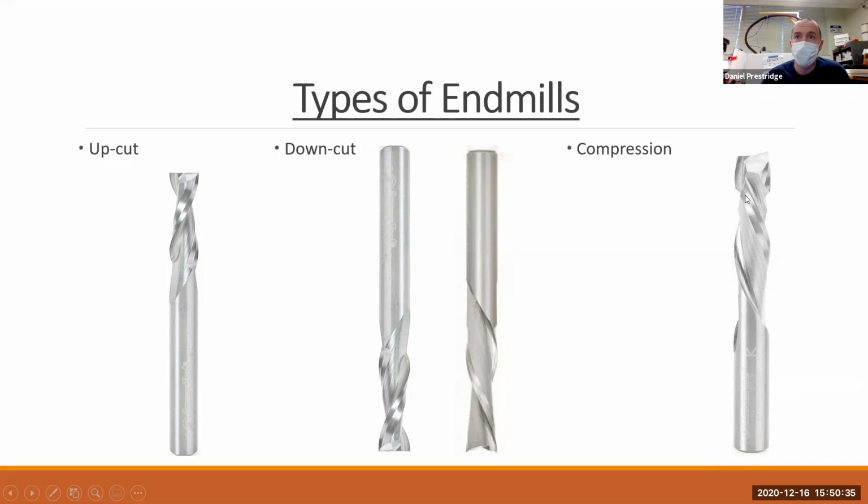That maintains the surface on the top of the workpiece because you plunge down enough that it's pushing down into it, but the upcut pulls up. So if you go all the way through the material and the bottom of the end mill is sitting at the bottom of your workpiece, then it doesn't push down through the bottom and create the same issue you would have if you were pulling up from the top. It's actually a pretty interesting end mill, but we really can't use it that much. It's more for wood and things that don't act like metals and plastics, where they get melty, stuck in the flute, and then they're done. They snap, they dull, all that stuff.